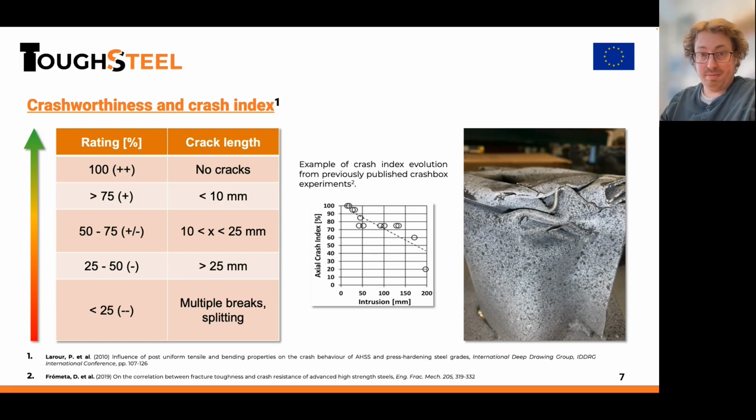And how to quantify crashworthiness? Well, there are several techniques, as David showed, but this is one of them. One way is to crush the component and evaluate the severity of the cracks at different intrusion depths. This is done with post-examination. You look at the boxes after the experiment, and then they rate the material accordingly using a crash index, one example of which you can see here from the Leroy paper.